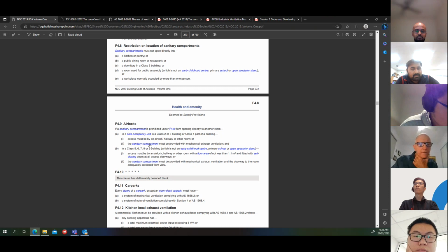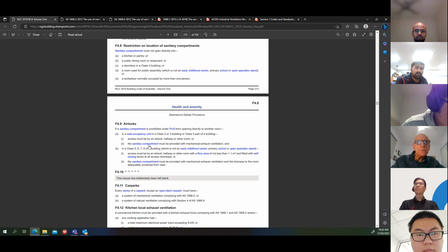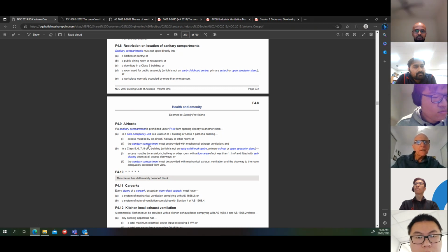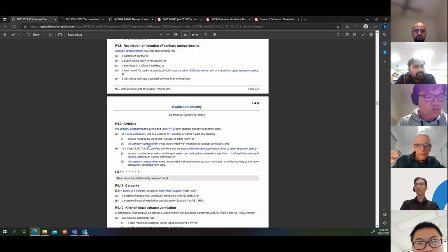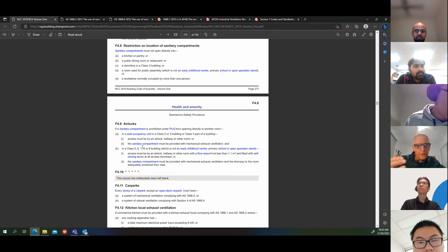See, look, I can't give you a definite answer on that. You'd have to have a look through AS1668 Part 4. It's more of an engineered solution. We've done it in car parks, and you can allow a certain distance in from the perimeter and call that natural ventilation, and mechanically ventilate when you're inside the building.